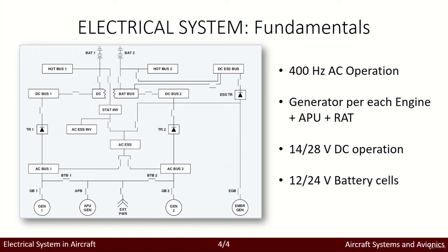Right, so as previously mentioned, electrical parameters are chosen to minimize the weight so the aircraft can get off the ground with its payload and gain altitude without expending unnecessary power and fuel, right? So one technique is to reduce the size and the weight of magnetics, which imply generators, transformers and motors, by employing basically a higher frequency power system.